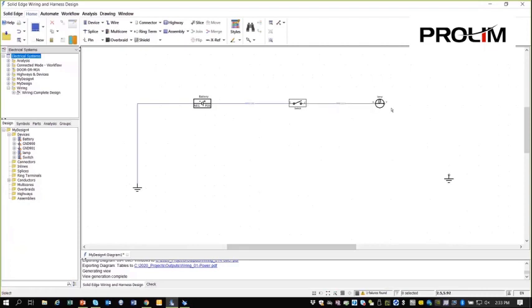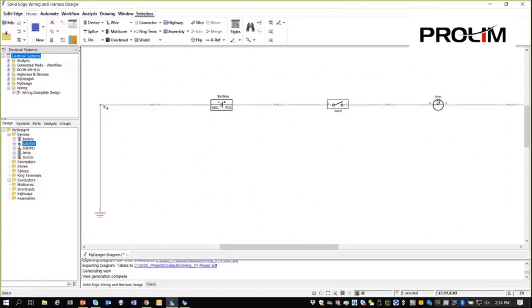But again, this is the intelligence built into the software. It knows what a wire is and how it needs to behave. And we see the names on all the wires, right? It's following some styling section that says don't put the wire name there unless it exceeds a certain length, so that's what it's doing. And then we look under the conductors here, and here's where we see our wires. And when we put down a wire, it's using the default properties of the wire there.